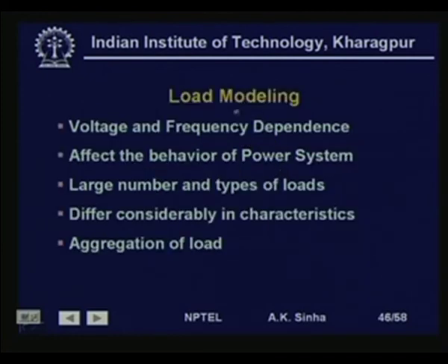Next, we will take up the load modeling. Loads have voltage and frequency dependence, and because of this change in voltage and frequency in the system, the value of these loads change and therefore, they affect the behavior of the system. We have a large number and different types of load which differ considerably in characteristics, and most of the time what we do is at any particular bus we aggregate these different types of load into a single load model.